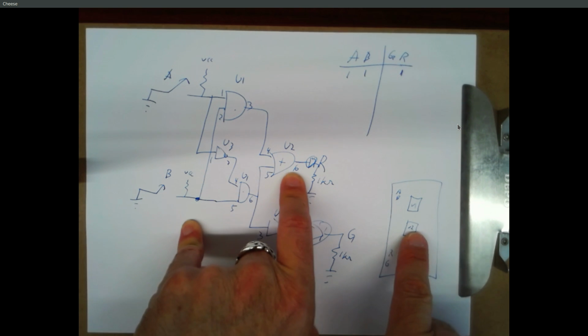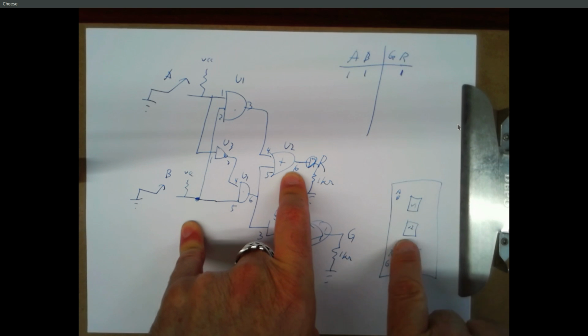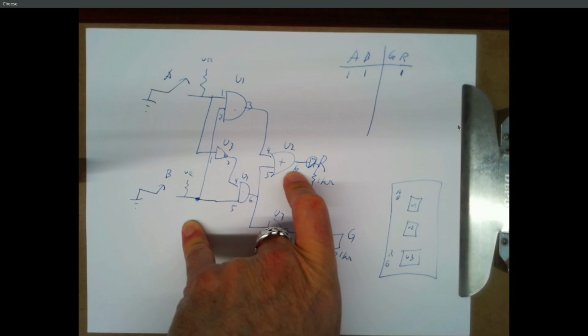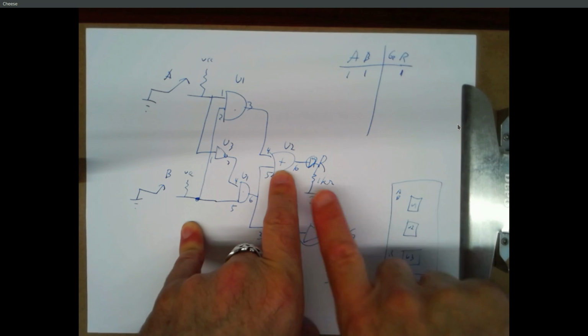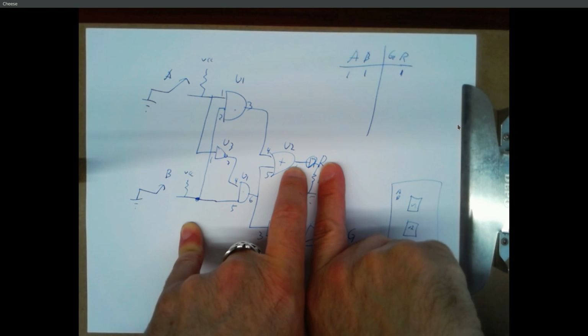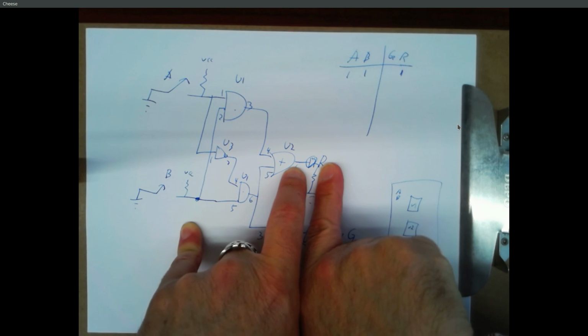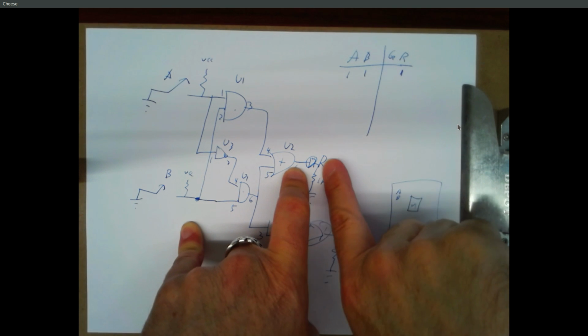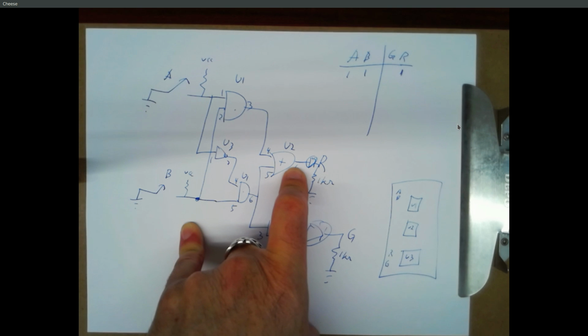So that's that middle chip, go to pin 6 of that, 1, 2, 3, 4, 5, 6, put your wire in there, read the voltage. If you're reading 5 volts, then you've got the correct output here. And the fact that the LED is off means one of a few things is going on. The LED is bad, the LED is backwards, or this side of the LED is not connected to ground.